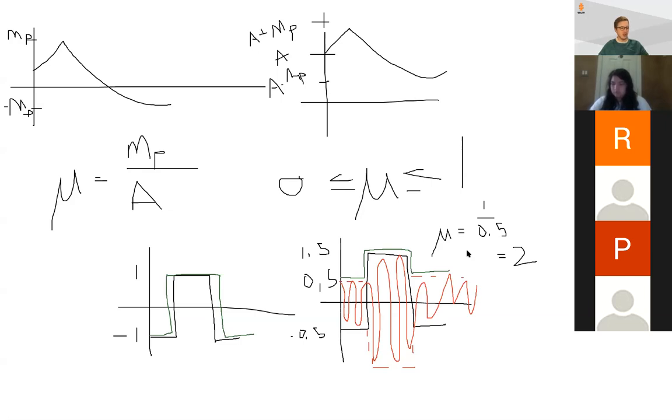That's why, if we have a phase modulated message with discontinuities, there are those big shifts in phase, because those discontinuities result in instantaneous phase changes. But for frequency modulation, it's a little bit different because you're directly modulating the instantaneous frequency with the message. But in neither case are you modulating the amplitude. I'm sorry, I said angle.